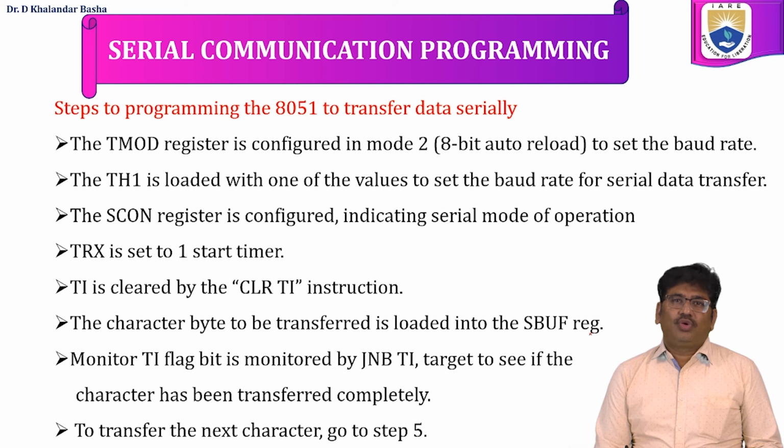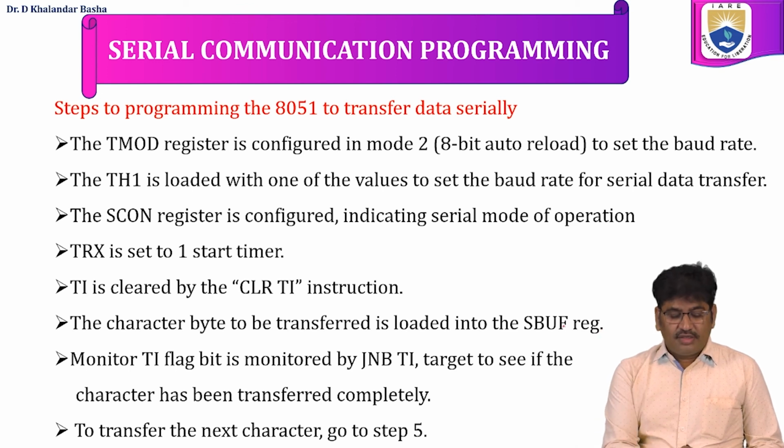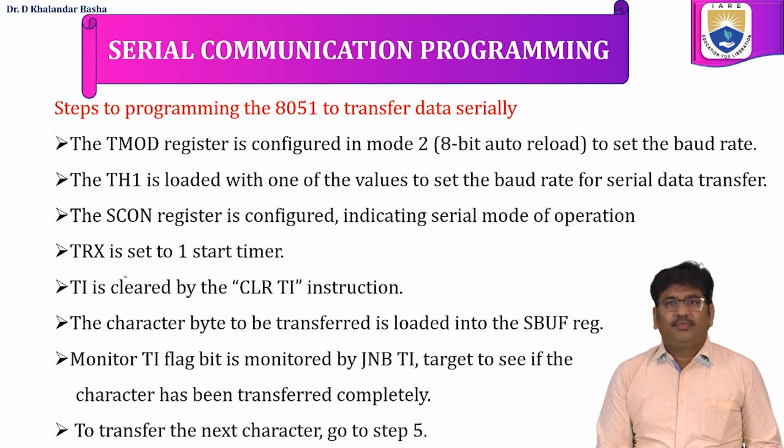The steps for programming the 8051 to transfer data serially. The TMOD register is configured in mode 2, that is auto reload mode for 8-bit case, to set the baud rate. The TH1 is loaded with one of the values to set the baud rate for serial data transfer. The SCON register is configured indicating the mode of operation for serial communication through 8051. Next, run the timer 1, that is by setting the TR1 bit to 1 to start the timer, timer 1 being usually used.